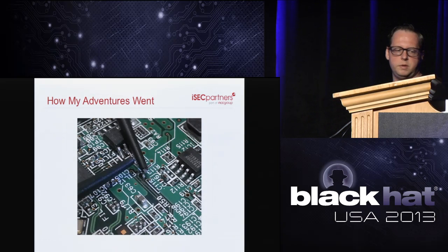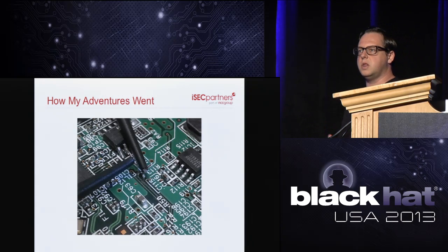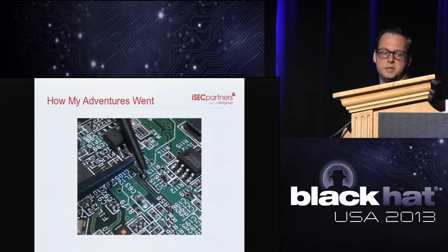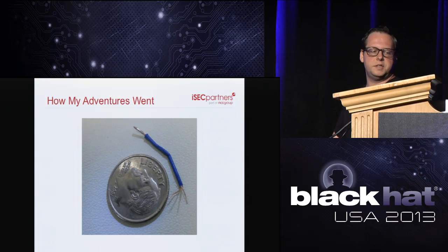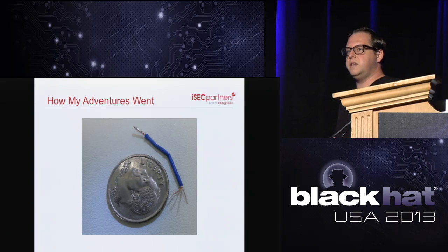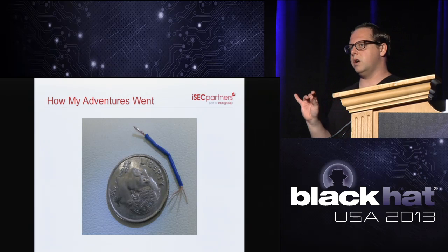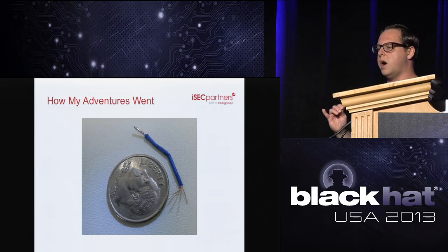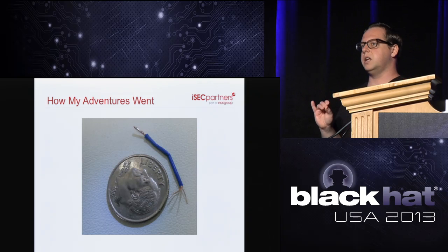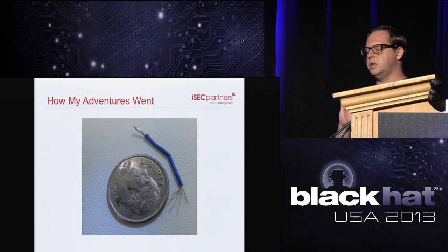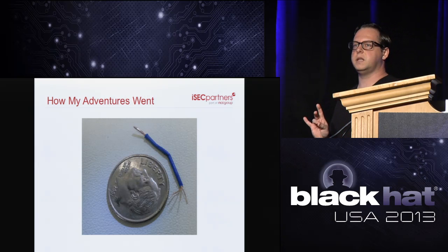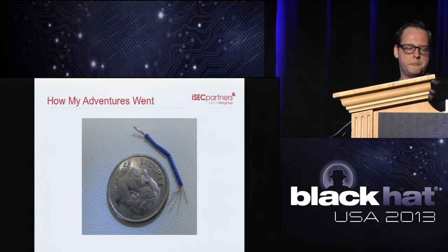Right here you can see we connected up the I2C lines to our logic probe. And we're going to start sniffing the I2C bus as well as other buses. And just for scale, here's the size of the wires that were going into these vias. And these vias fit these wires perfectly, almost to the point where tinning the wires almost wasn't an option. You had to have just the smallest amount of solder on these wires to get them to fit in the vias perfectly and then solder them in.